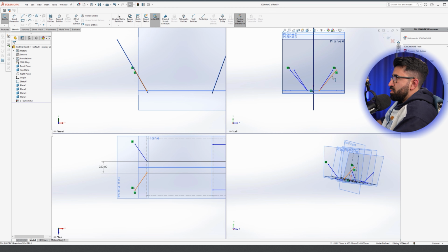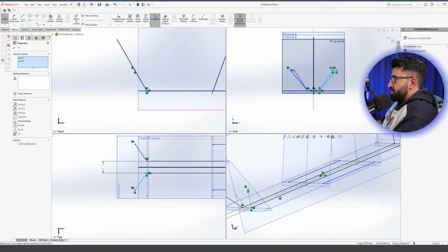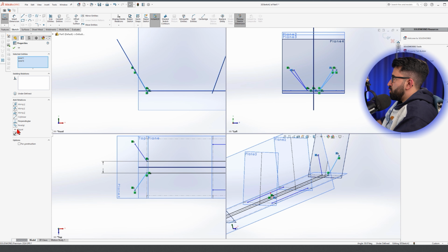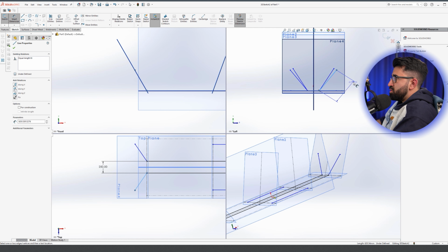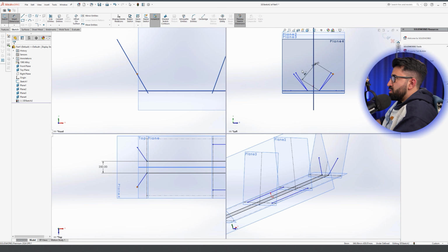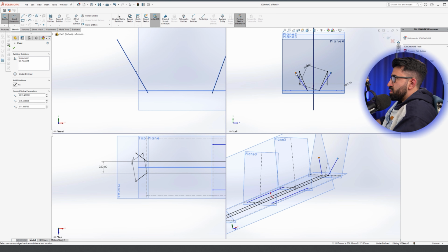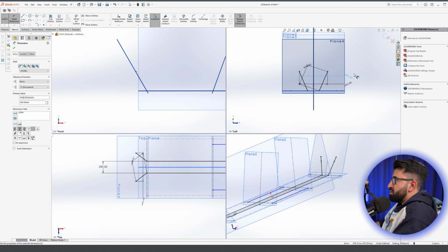Let's just make this one and the one on the back. I'm selecting these two, by the way. One in the front and one in the back, and make them equal. Now assign one dimension to the front. Let's just say 500, half a meter. And the distance from here to here, 600. Same with this one, 600. So front and back, 600, fully defined sketch.